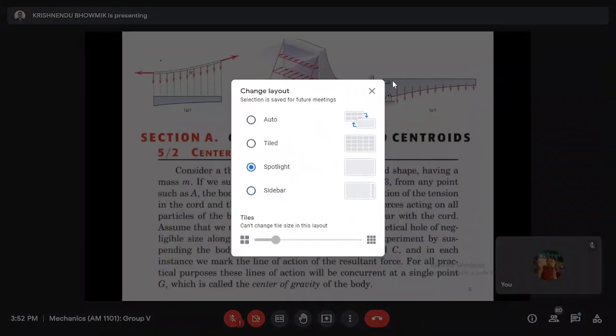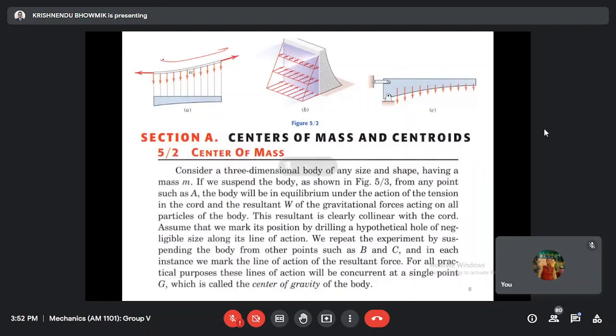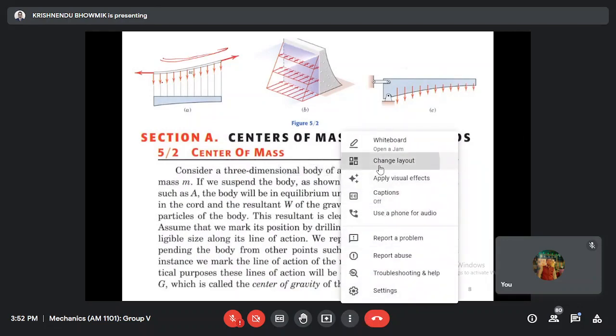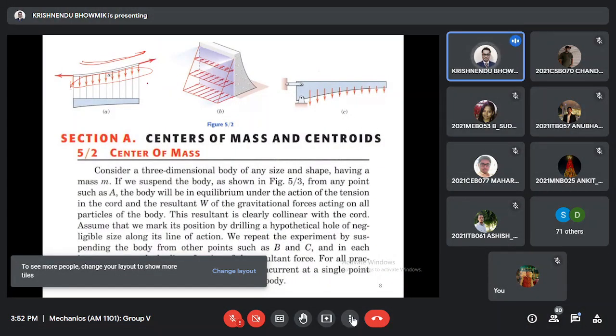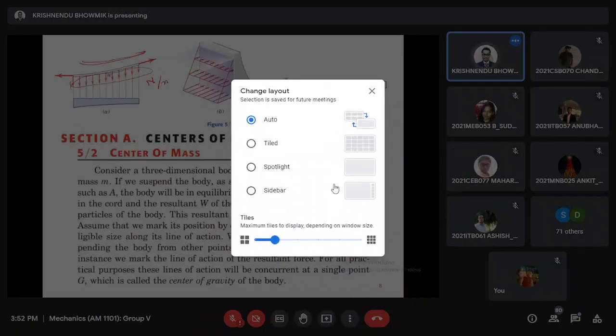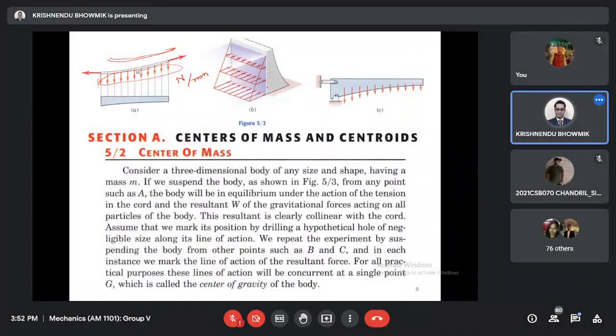Similar way, say I have a cable having its own weight, for example, and this is the distribution of the weight. It is acting as load per unit length, say Newton per millimeter, a line load. Here it is pressure, so based on the depth, pressure is increasing. Then maybe we have some sort of distributed force like this, and we can calculate the centroid of those forces using the first moment principle.